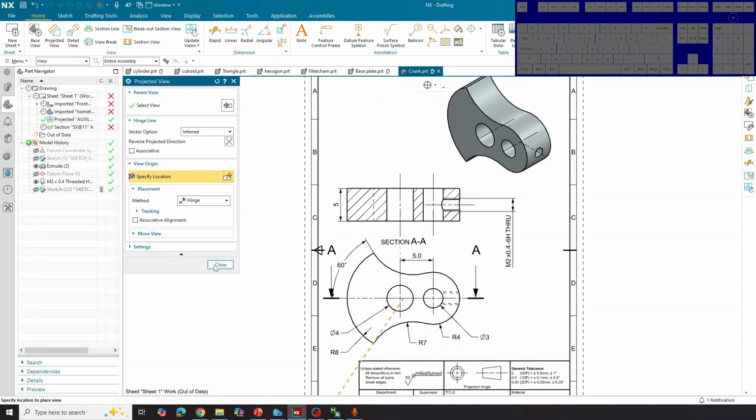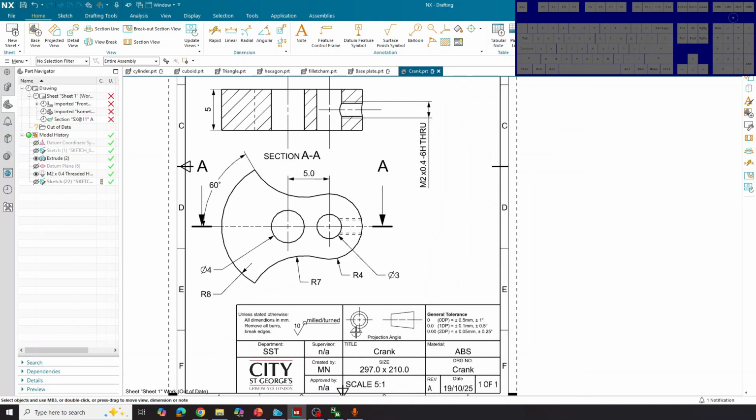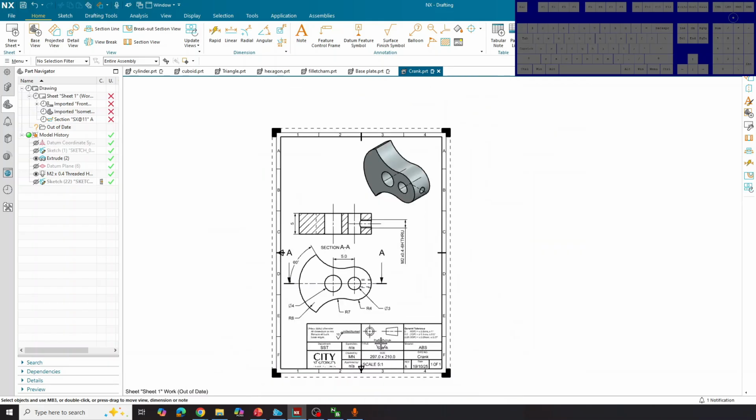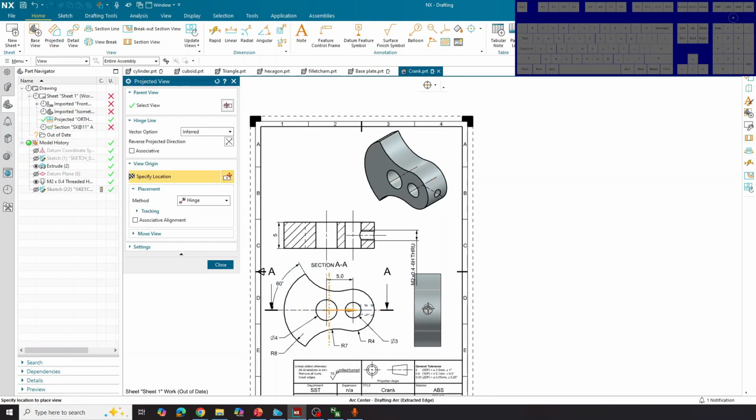Now the version that we use is third angle projection, and that's denoted over here. This is a projection that mainly America and some parts of the UK use. So what it basically means is, if you want to look at this part from your front view, like over here, if you want to look at its right side, then the displayed parts will appear on the right side as well.